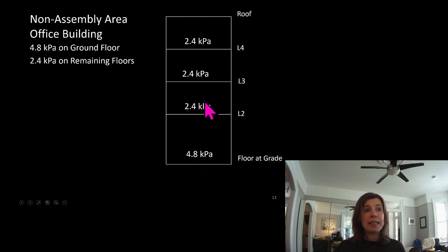Another good reason is if there is a reason to exit the building, you can have everyone from those 2.4 kPa floors coming down onto the lobby floor simultaneously. So you can very easily end up with 4.8 kPa down there.